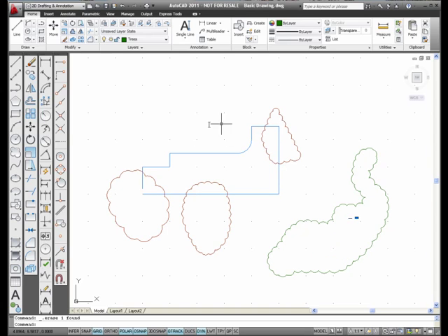Notice what it did when I did the polyline. Let me try it again. I'm going to go ahead and select. The opening is right in here. I'd probably turn my polar tracking off. And what I'm going to do is I'm going to select RevisionCloud. I'm going to type in O for object. Press enter. Pick it. There it is. Reverse direction. Sure. And there it is right there. This is for civil engineering.